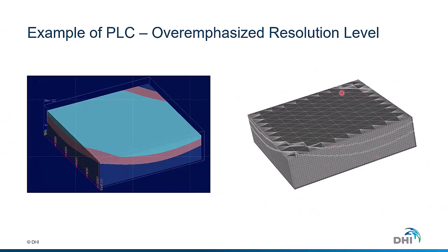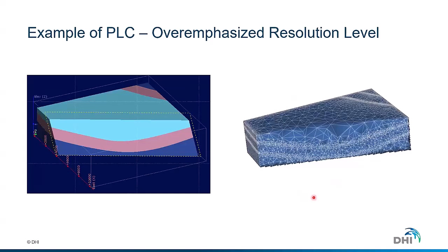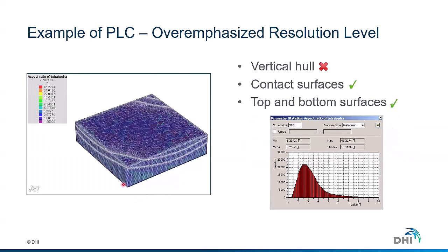And this is the input data set we are using for creating a tetrahedral mesh. Sometimes it works, sometimes it doesn't. What I will discuss today is a number of alternatives on how to overcome this problem. If you take this input surface triangulation as it is, you end up with a representation of the geological context as you expect, but also a drawback: on the vertical faces there are extremely small tetrahedra because the original surface mesh comes in that way.